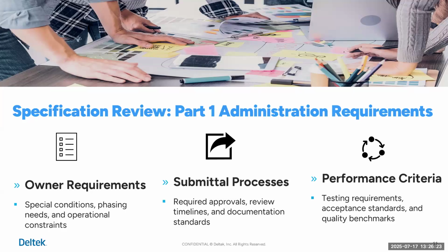So during the duration of the project, it's important that the project team work with the CA person and the specifier to coordinate and clarify which submittals are for approval. The submittals are either going to be for approval or reviewed for conformance versus the items that are for information only. And it's important that those things are reviewed so that the contractors understand expectations.